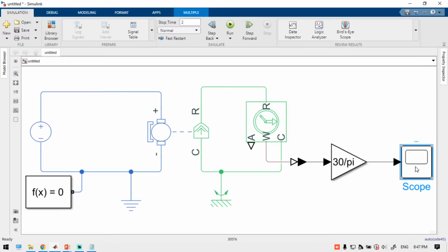This will not reach zero or maximum instantaneously when you apply the PWM. But the average power will be applied to the motor. Due to that, we can control the speed, right?